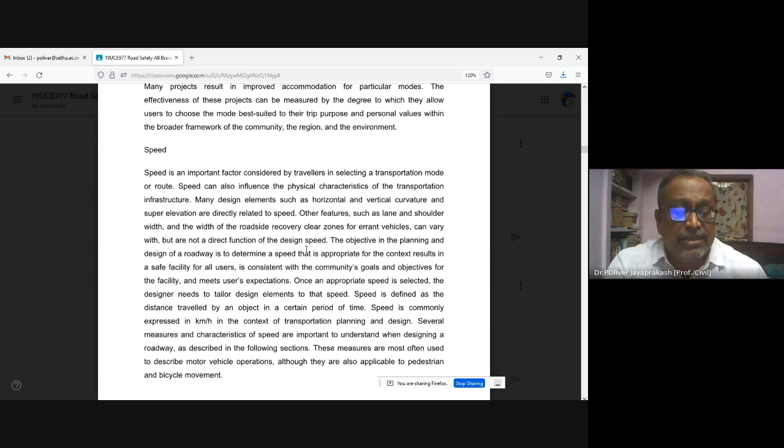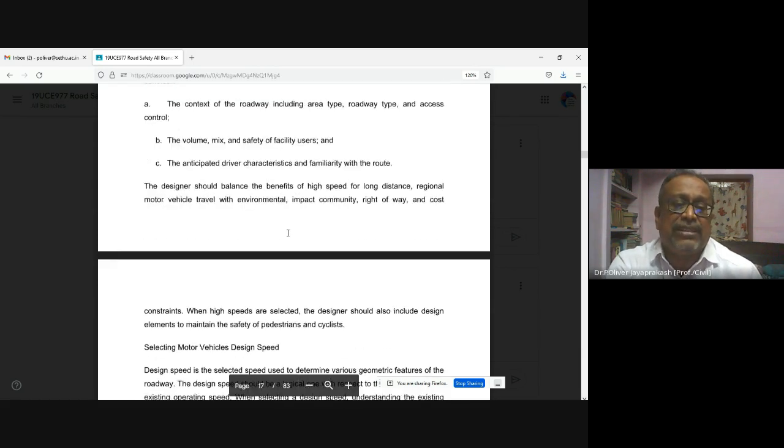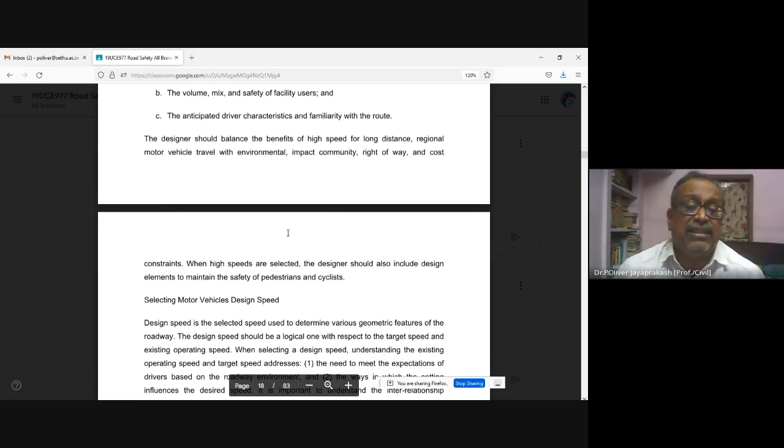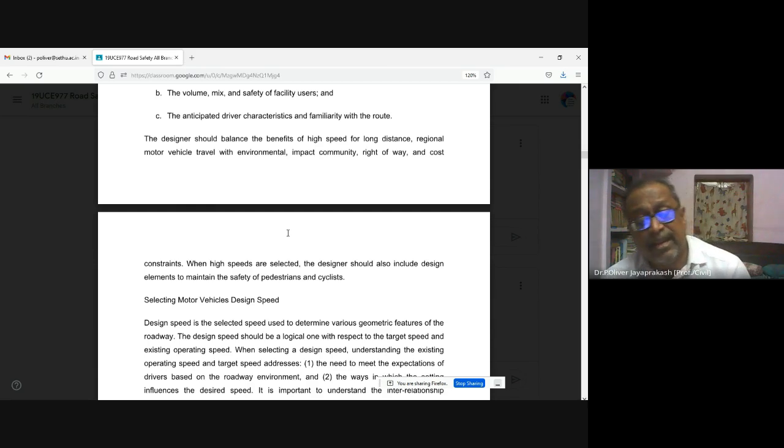Okay. So in today's lecture, we have seen the factors influencing road accidents or incidents. That is your road user characteristics, driver characteristics, road characteristics, in addition to your environmental conditions. And the more important thing is your psychological and environmental characteristics, because they govern the braking distance, speed, side distance, maneuverability on a curve, negotiating the curve, and the safety of pedestrians or cyclists on the road. So these factors are more important compared to the other factors.